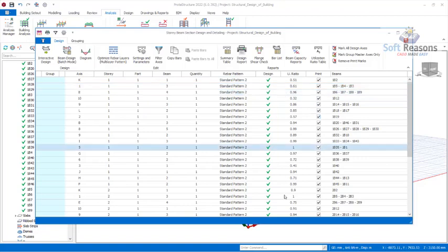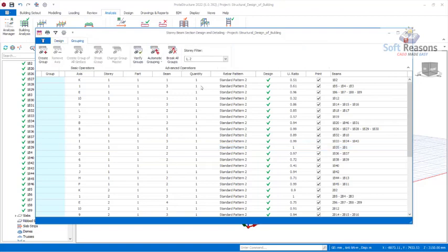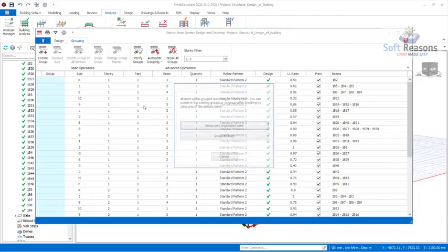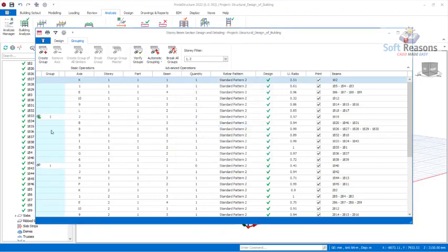The same thing applies to all of that, just as I've said earlier. And also, you can come to grouping and be able to do these beams. It all depends, but we wouldn't have many similar beams here to group. If not, you come to automatic grouping, and then you can group beams within floors, okay? So if you click on that option, click on apply. So this is going to group beams within floors.